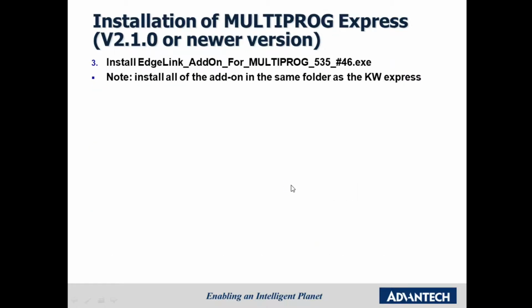And third, install the EdgeLink add-on for MULTIPROG. Note that the user needs to install all of these add-ons in the same folder as the KW Express. This add-on will help the user to use MULTIPROG with EdgeLink project importing.